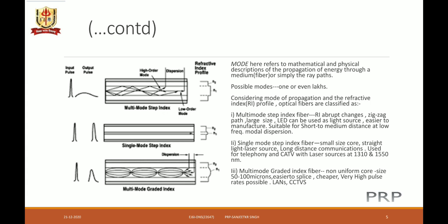LED can be used as light source because the core diameter is large and it can gather light from a wider angle. Light can be injected into the fiber easily and it is easier to manufacture. So this type of fiber is suitable for short to medium distance and at a low frequency of data rate.